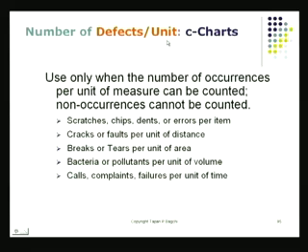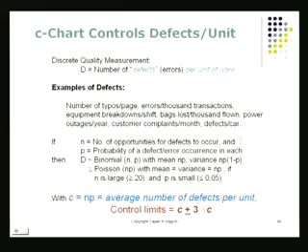So the unit you set in a manner that makes sense to you, find the number of defects you produce, and the rest of it is very similar. I will just remind you of one thing there. We are using the 3 sigma limit. In the case of x bar, we were able to comfortably use the normal distribution because the central limit theorem told us the average approximates a normal variable, and therefore there is no real issue there. You could use the 3 sigma limit there.